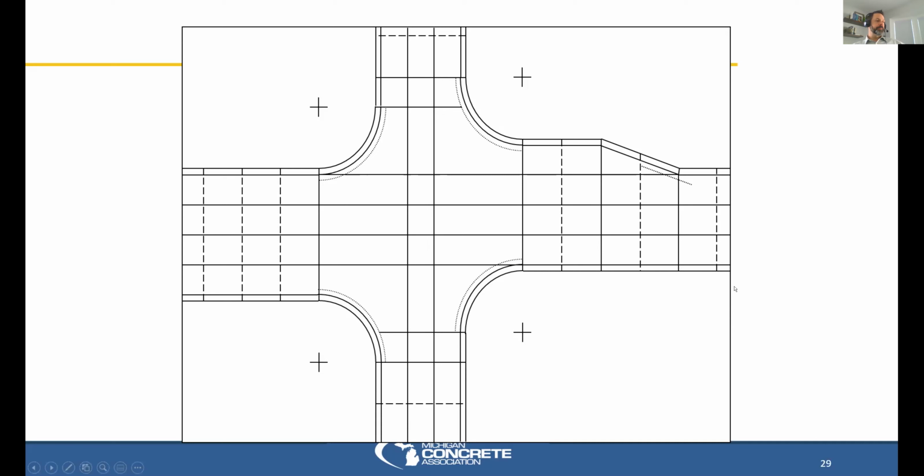Steve, it says, are we still using expansion joints? We are still using expansion joints as isolation joints to isolate one east-west pavement from a north-south pavement, or to isolate the bulk of the parking lot from the entrance drive, or to isolate the 10-inch loading dock from the 6-inch parking area that butts up against it. Yes. Are we using expansion joints at regular spacings within concrete?